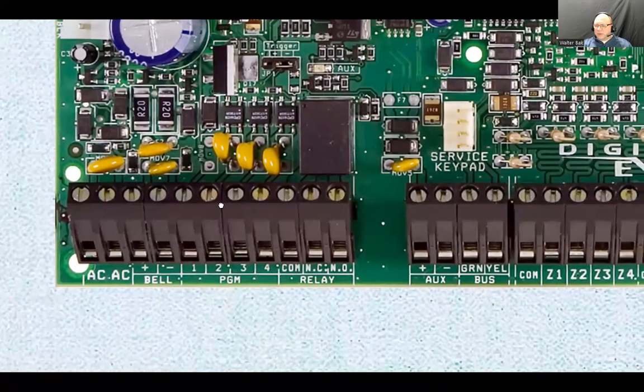I'm going to analyze this from left to right. AC. This is where you plug in the power. And for the most part, the doorbell transformer is going to work. It's about 18 volts AC, and there are transformers sold that could be wired in or plug-in transformers. A plug-in transformer is basically a half-a-brick looking thing that has the prongs for the receptacle. You plug it in, and it has screw terminals that you can connect the two conductors to, and they connect right there. I'm pointing at my screen here, right here.